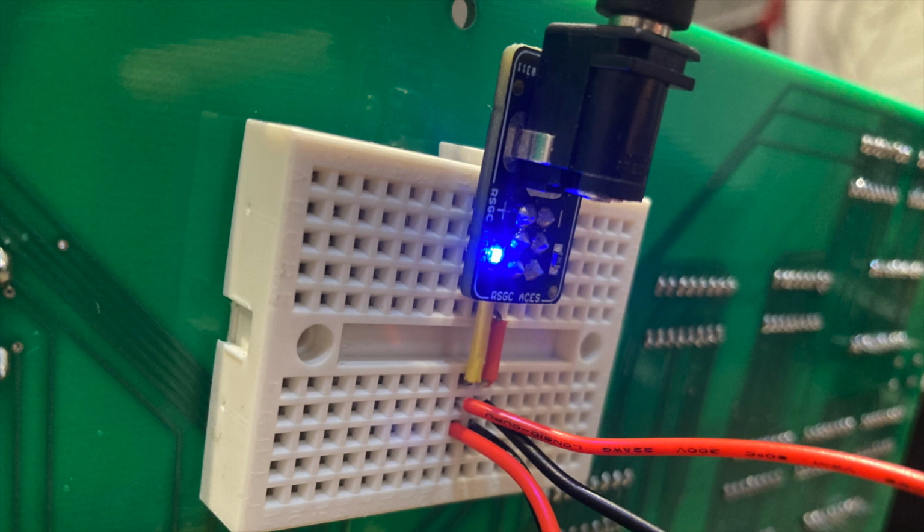Given the power requirements for this project, power should be sourced from an external 5-volt source rather than from the Arduino, as this would cause damage to the many voltage output pins. The external source of voltage can be used as an input source of voltage for the Arduino. This is only a temporary solution until the next stage of this project.